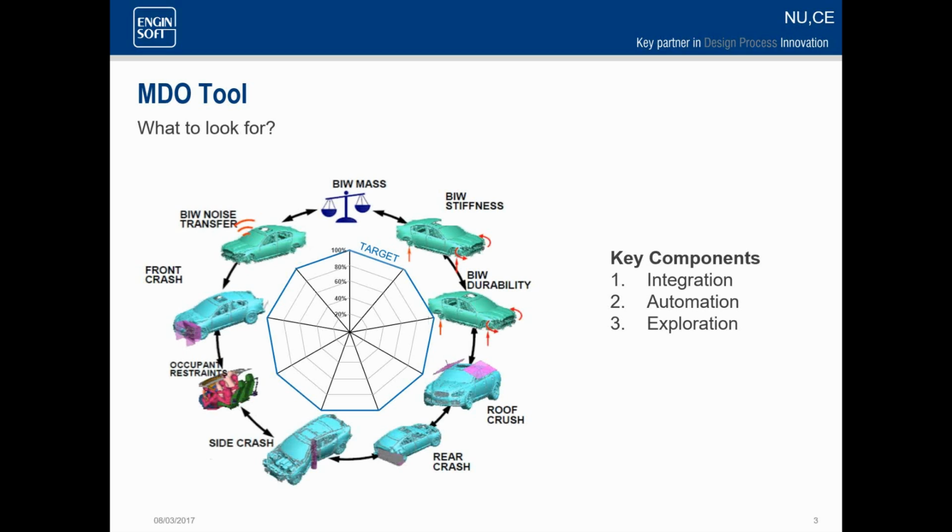So just to get you up to speed, modeFRONTIER is a multidisciplinary optimization tool. Typically when you're designing something, you've got some targets, maybe a set of disciplines you're looking at, and we might analyze that and have some baseline value. If we were doing something a little bit more smart, we might do some optimization, maybe a single discipline optimization, but typically improving one of those disciplines comes at the detriment of other disciplines. When we're looking at MDO, we're trying to push all of our disciplines, get a balance between them and optimize them in all directions.